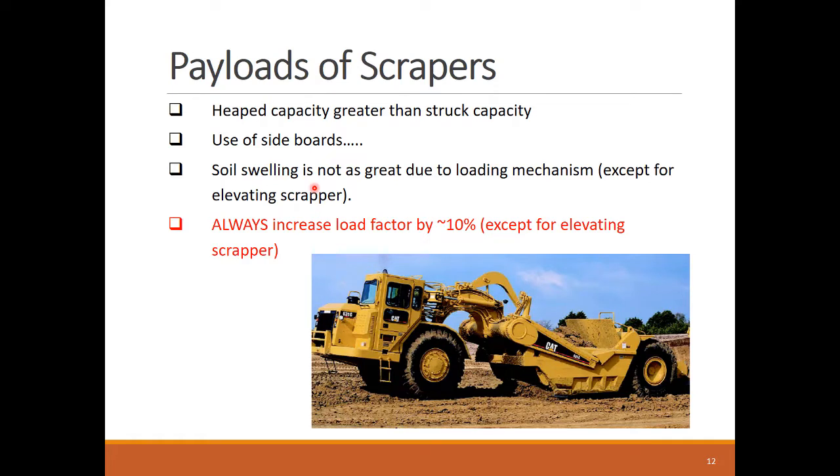As for all earth-moving equipment, we need to relate its payload to the soil bank volumes that are being cut. Heaped capacity of the scraper can be achieved by using sideboards, but unlike trucks, the soil in a scraper bowl is not completely in a loose state.